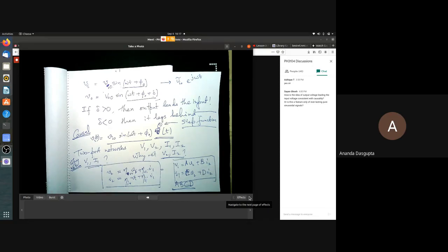Now that's possible if your circuit is in a black box sitting in front of you on a table, let's say, and you want to experimentally measure stuff. You can in principle do it. In practice, you never put a short across a pair of terminals which is sticking out of something, because that would be potentially risky. But you can at least imagine doing that, and if you are not putting in a short, you can always put in some resistance and vary the resistance and see how the currents are changing. This is where you have access to both the input and the output.